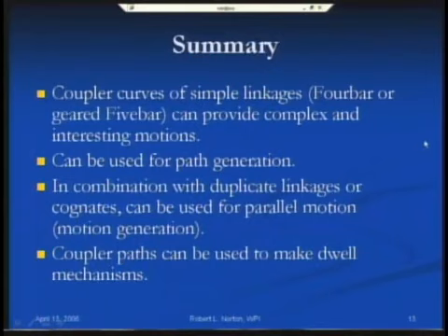The coupler curves of simple linkages, I'm talking about 4-bar and geared 5-bar here, can provide very complex and interesting motions. We can use those for path generation, which is what we've been looking at today. By that is meant I'm moving a point along a path. When I'm considering path motion, I'm not really concerned about the orientation of the link. That, however, could be a serious issue.